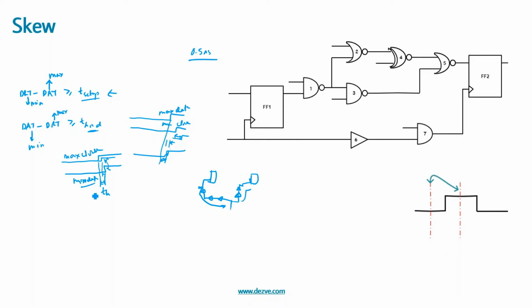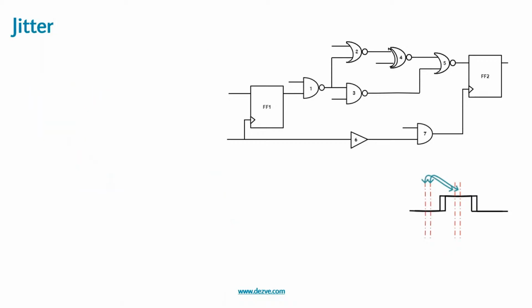Now there can be various uncertainties, okay? There can be uncertainties because of the clock path skews. There can be uncertainty between subsequent edges of the clock because of the clock's jitter, and there can be some process variation for which we have to keep a margin, correct? So jitter is a periodic temporal variation, correct? Temporal variation across subsequent clock edges.